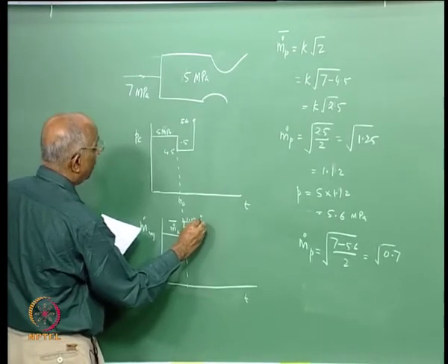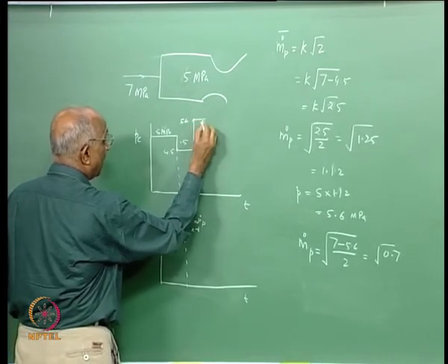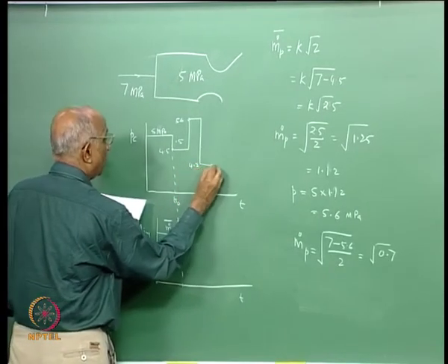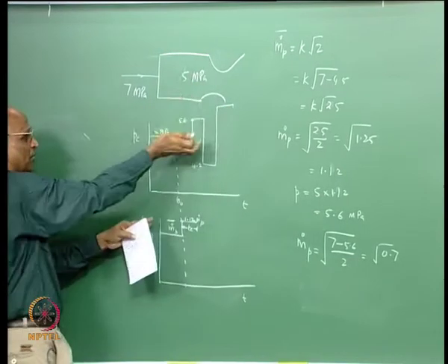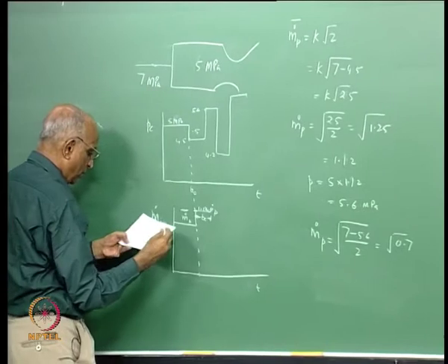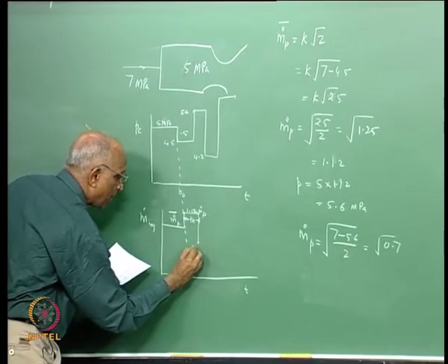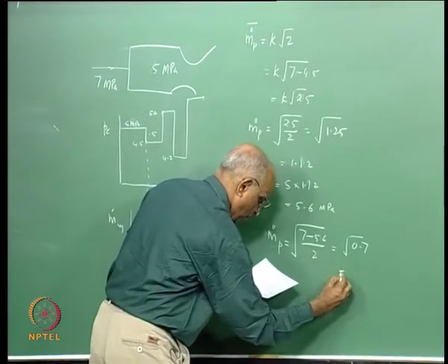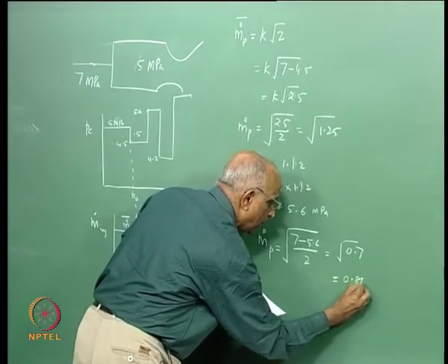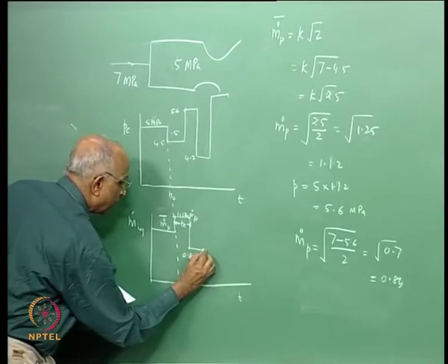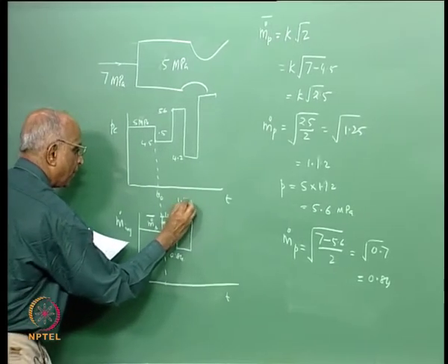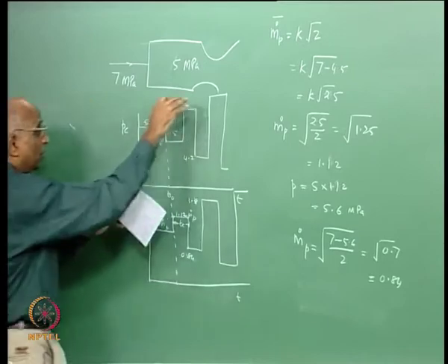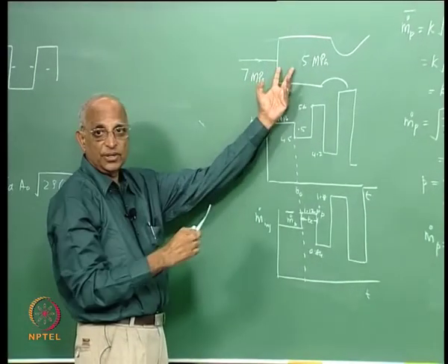When it has burnt over here, after this maybe I have a delay time during which the pressure now comes to 4.2, and then after 4.2 it goes still further, and therefore it could even diverge, it could keep on increasing the value, and here if I were to put it down, it is 0.84, this value 0.7 is 0.84, and from 0.84 it picks up and goes to 1.18, and then it keeps increasing, and therefore even the oscillations need not be neutral, it could keep on increasing depending on this pressure difference.